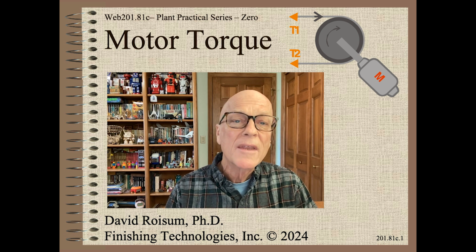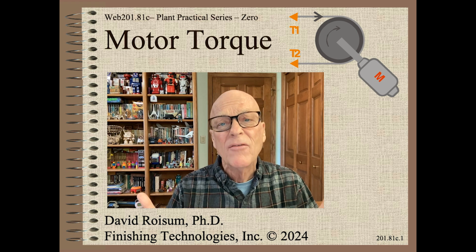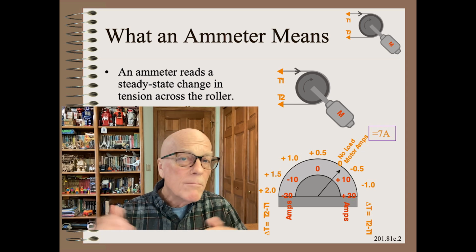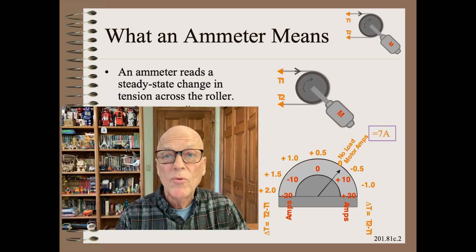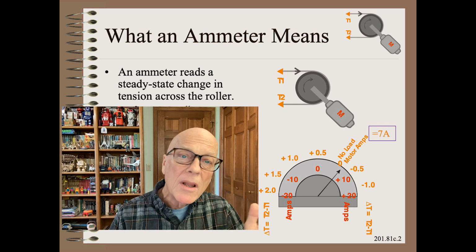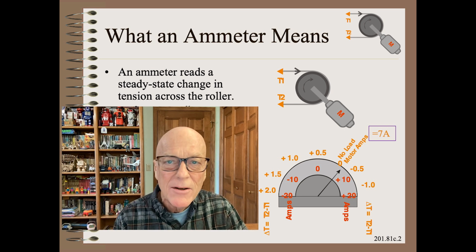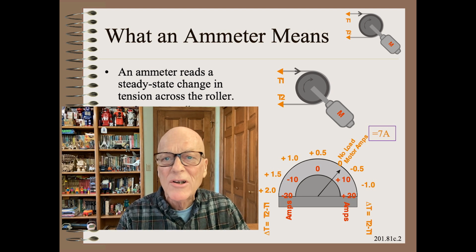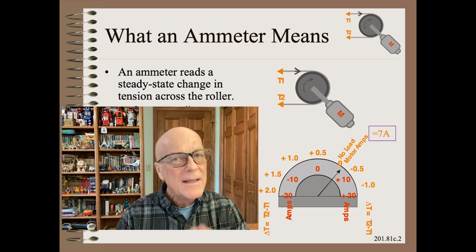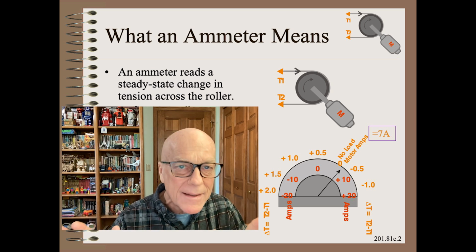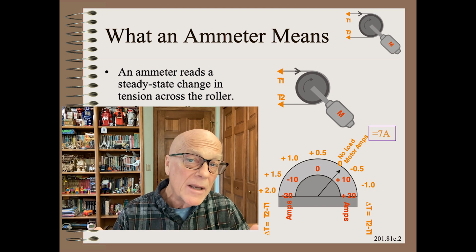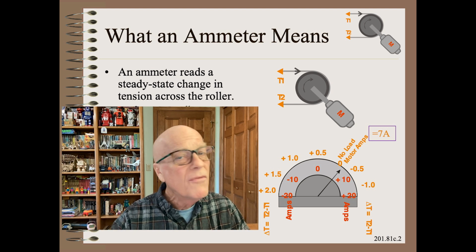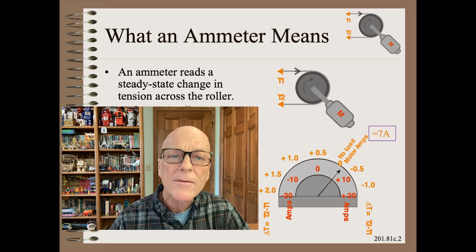Let us begin with the DC motor ammeter that effectively mirrors motor torque. Below on the right is an example ammeter that can read from minus 20 to plus 20 amps as shown on the inner scale. Note that AC vector drives and servo drives may display torque directly as a computational model, but the principle we describe here is exactly the same. To understand the ammeter, we must first define zero in web handling and then friction before any calibration can continue.